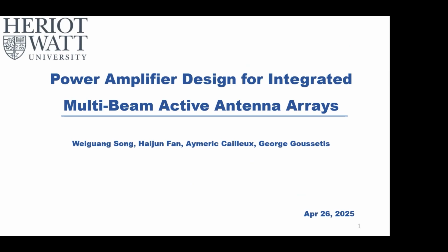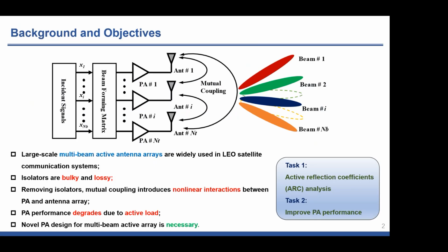We'll present our work on the power amplifier design for integrated multi-beam active antenna arrays. As introduced by Aymeric and Jiayu, our background is that in the large multi-beam active antenna arrays used in satellite communication systems, it's a trend to remove the isolators, which will cause performance degradation of the power amplifiers. So our problem is how we could improve the PA performance degraded by the removal of the isolator when the PA is presented to the active reflection coefficients.